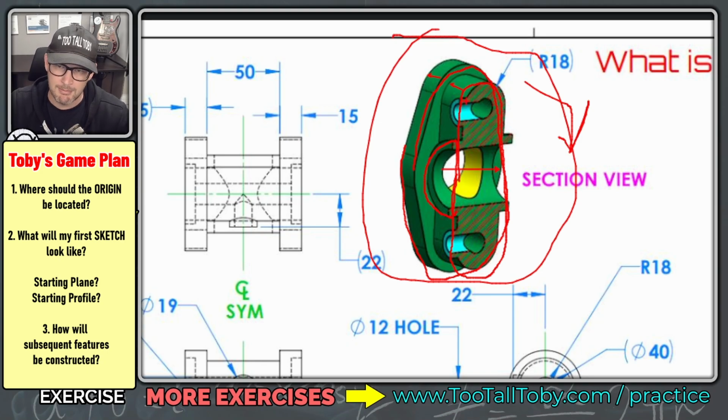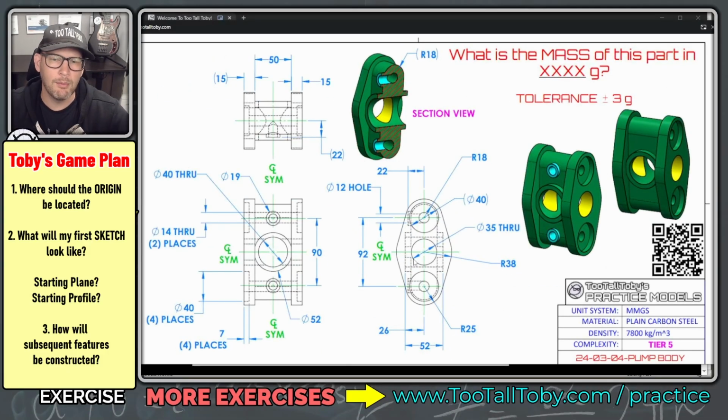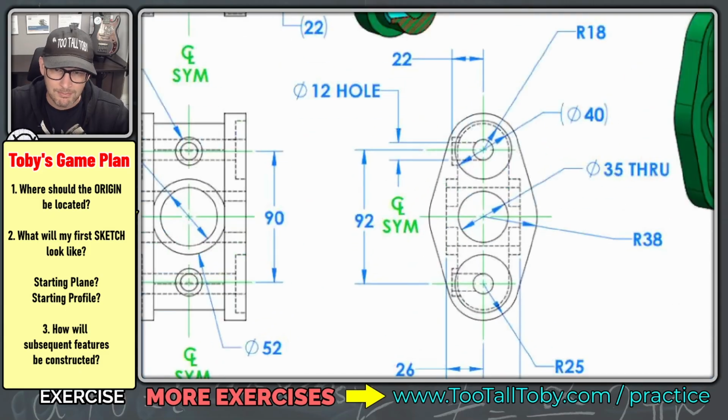And then I'll create the geometry for these sleeves here, these little solid sleeves. Whenever you're working in 3D CAD, you always want to start with your solid geometry and save your cuts for later in the design, especially when you've got overlapping geometry like we're going to have in this model here. So do your solids first, then do your cuts at the end. Now, the final thing that I want to mention about this design is that there is something that's a little tricky.